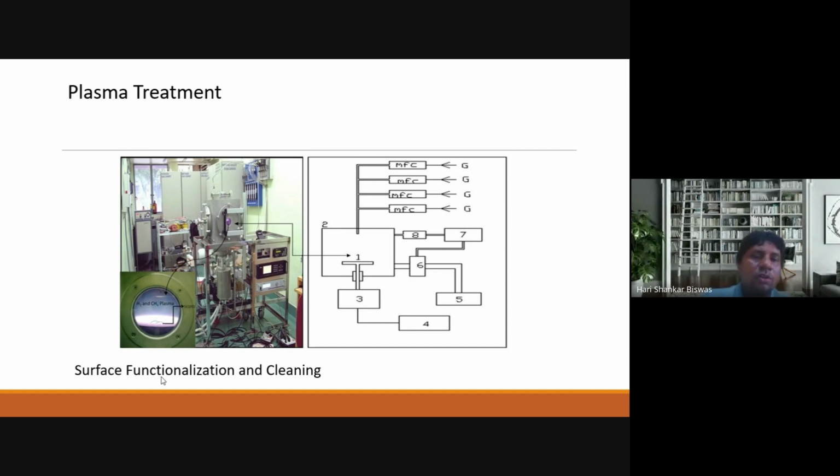We just use the plasma technique, and we also do not require any high temperature, because we just use radio frequency. By this radio frequency, we can break the carbon-hydrogen bond and carbon-carbon bond also. And under plasma condition, it can be deposited on silicon oxide.